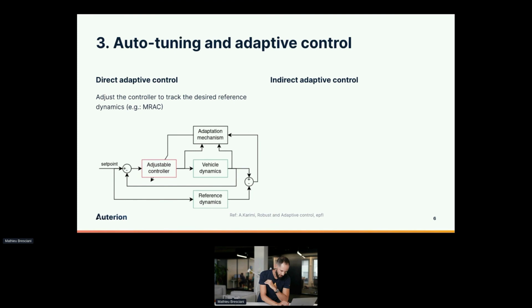Second one: what's the role of the model estimation block? It's just to provide you a mathematical model, to then create the PID controller gains. To do that, when you estimate, you get your discrete time model with a set of parameters, and from those different coefficients, you can put them in an algorithm that will generate the PID gains for you. That's why you need to build the model first in the case of indirect adaptive control. You first need to build a model to know what you have to tune in a mathematical sense, and then you can design the controller from it.